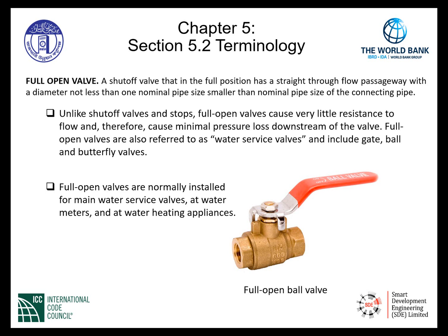Unlike shutoff valves and stops, full open valves cause very little resistance to flow and therefore cause minimal pressure loss downstream of the valve. Full open valves are also referred to as water service valves, and they include gate valves, ball valves, and butterfly valves.